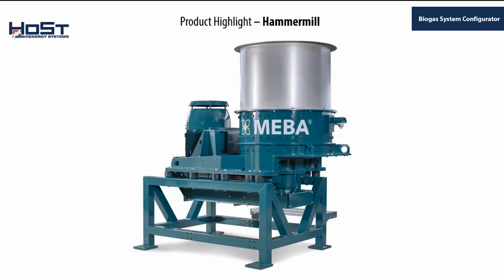Next, we talk about the hammer mill. What is the hammer mill? The hammer mill takes the solid feedstock and shreds it up. It breaks it down. This is important for 3 reasons. One, it makes it so we can, in the next step, pump the feedstock into the digesters, which is handy for feedstock handling. Secondly, it avoids clumping and floating layers inside the digesters when we shred it up like this and pump it into the liquid layers.